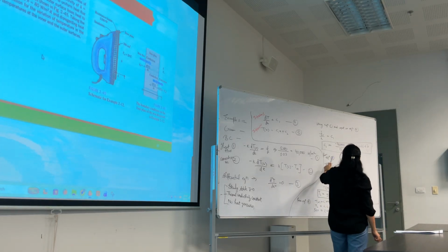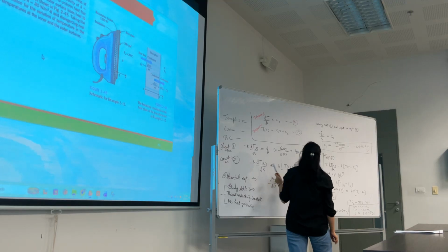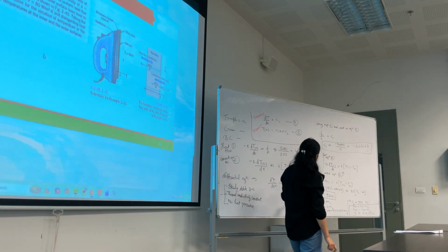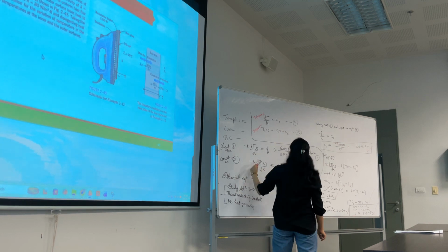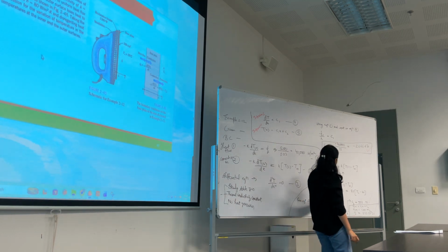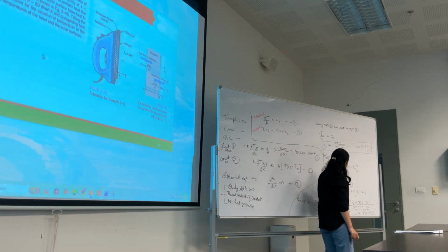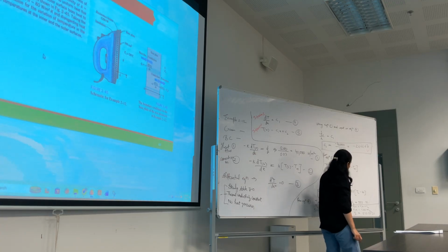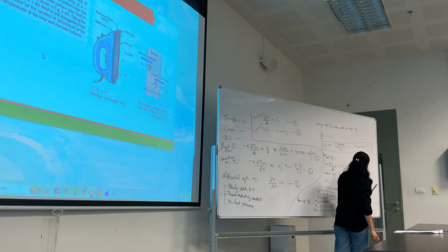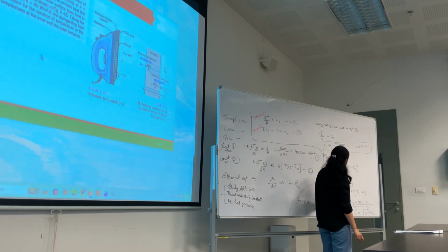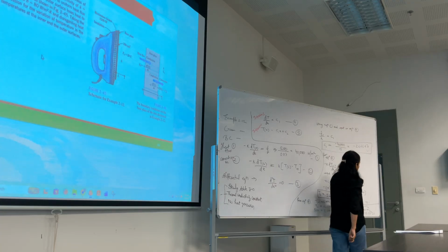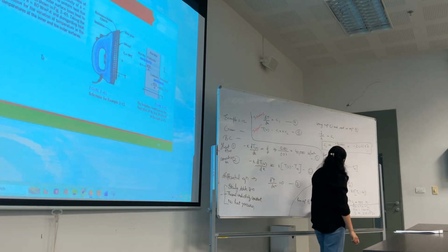Alright. From equation 2, we know dT over dx can be written as C1. Then the value of h is given in the question, the value of T infinity is given, and the value of K is given. C1 we just found from here. You input everything here and we find the value of Ta.